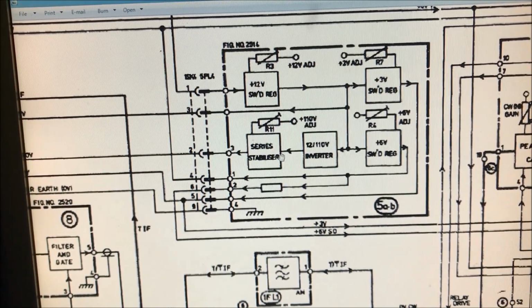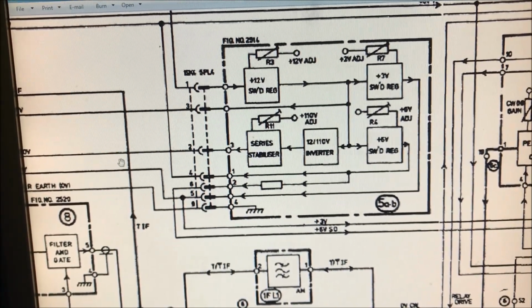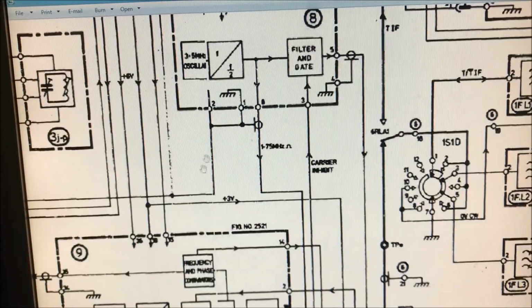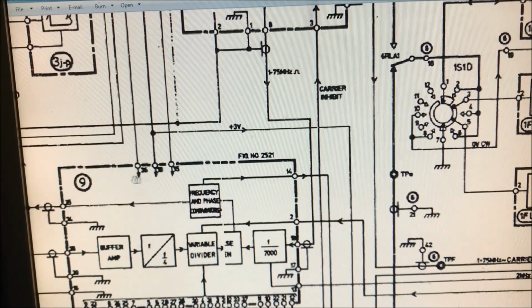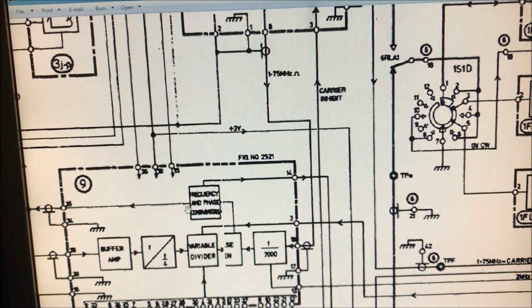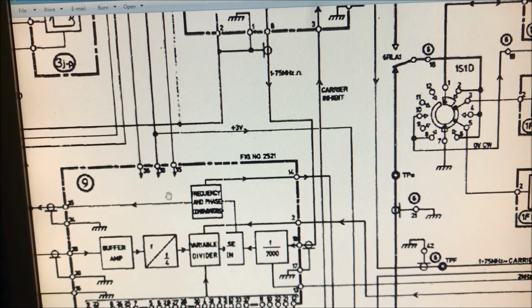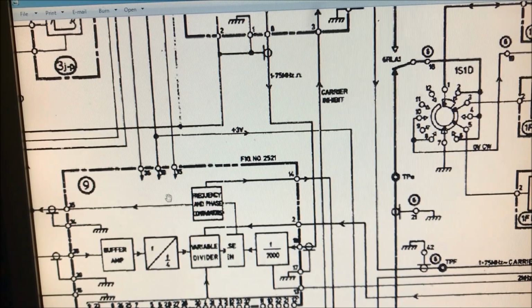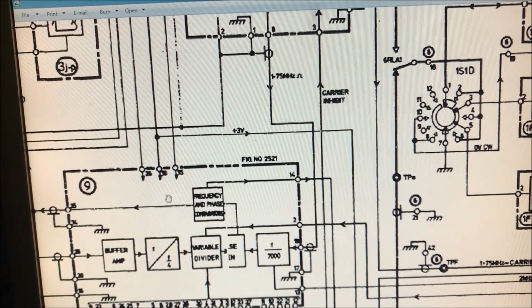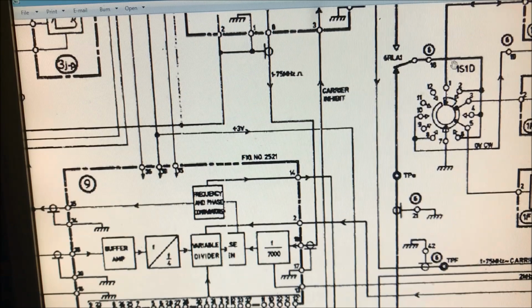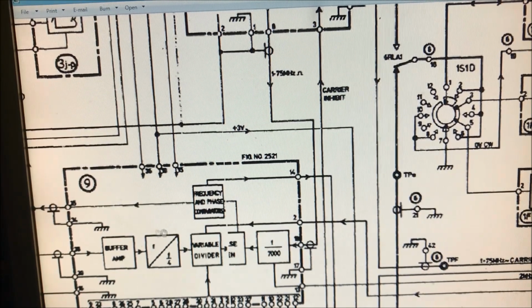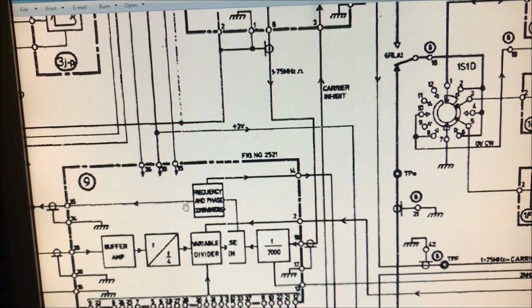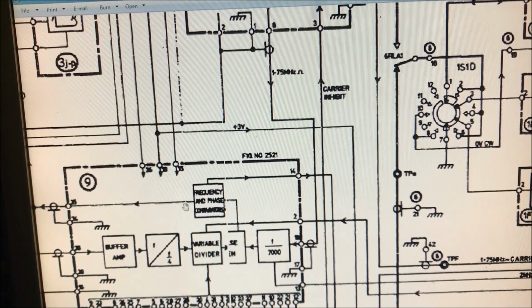Okay, but down here on the synthesizer, where the 110 volt goes into the synthesizer, on the top board of the synthesizer lives two more capacitors, and they're about 10 microfarad capacitors, and they get old and weary as well, two tantalums. And when we change the two on the power supply, it's always recommended to change the two on here. Okay, and they're the smoothing capacitors for the 110 volt supply.